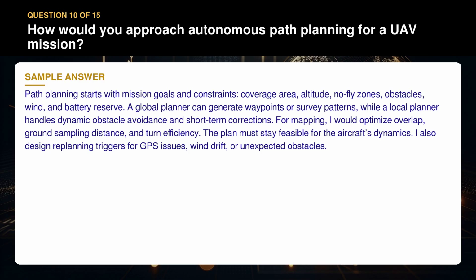For mapping, I would optimize overlap, ground sampling distance, and turn efficiency. The plan must stay feasible for the aircraft's dynamics. I also design replanning triggers for GPS issues, wind drift, or unexpected obstacles.